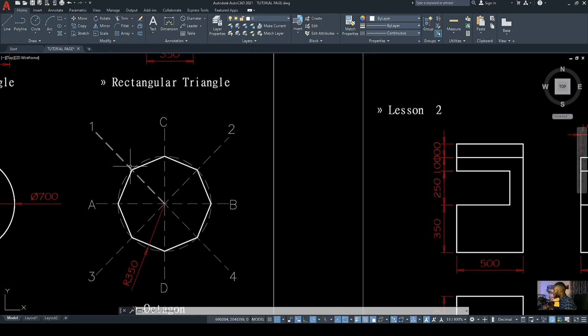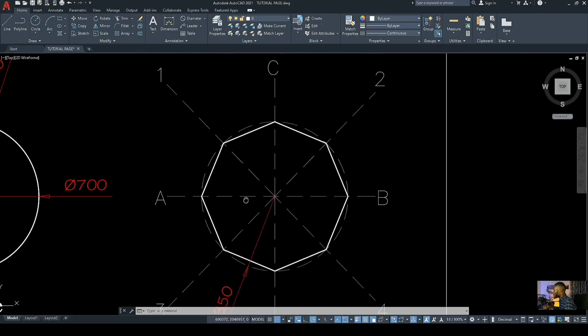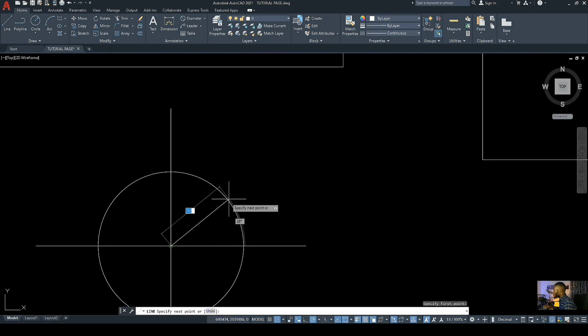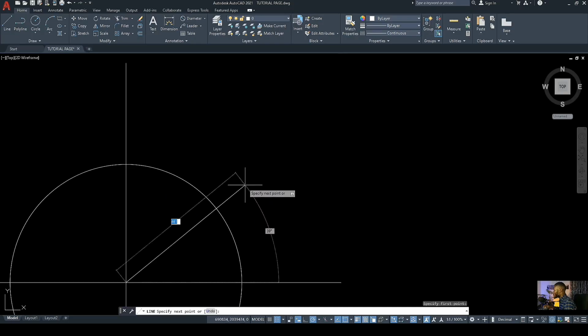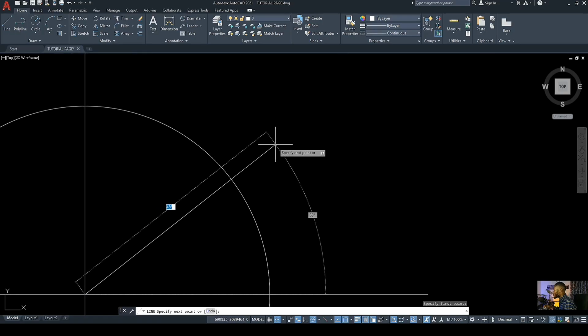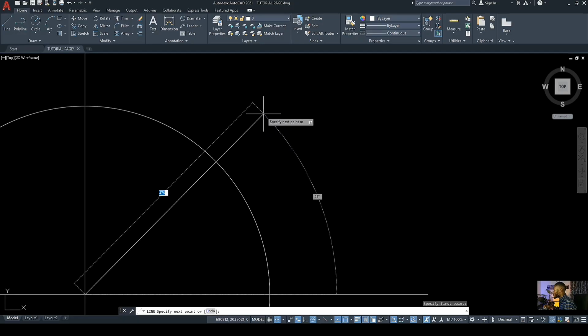Then to create a bisection, sharing the angle into two equal halves, we'll be left with 45 degrees at this point and 45 degrees at this point. So what are we going to do? We just pick our line tool again. We pick the center, then navigate to see where we have 45 degrees. We'll be looking at this arc showing in degrees. You'll get to 45 degrees. There's another way of doing this, but let's go through this process for better understanding. So at 45 degrees, you click, then press your space bar to uncheck.